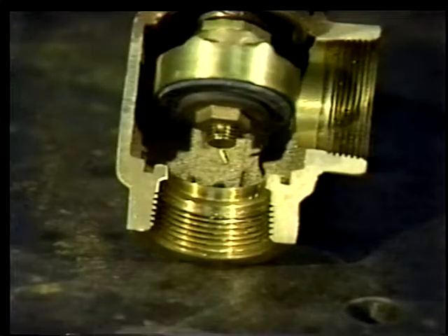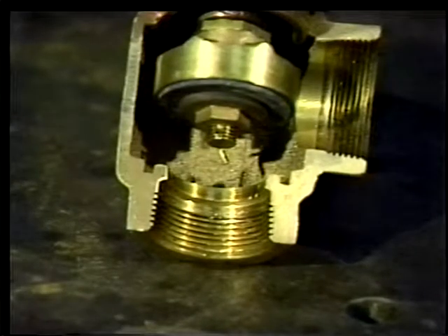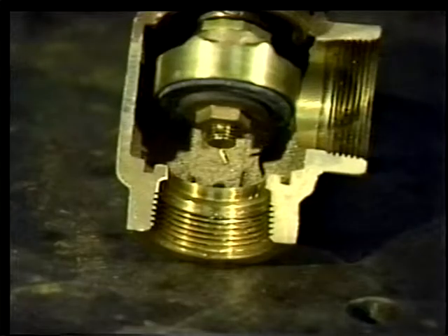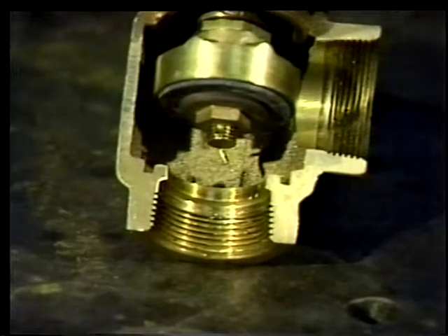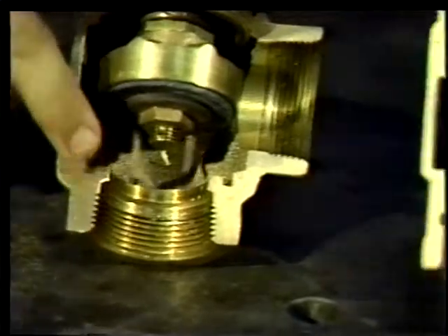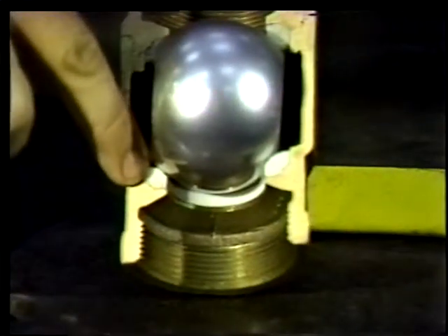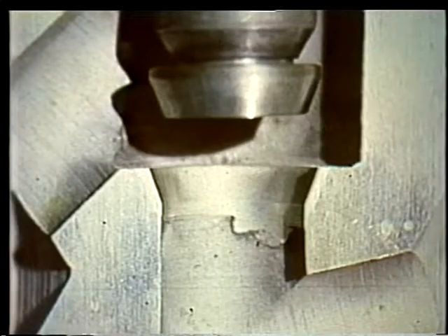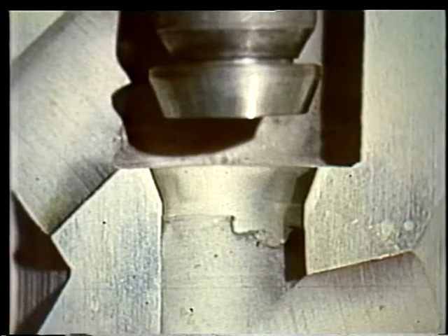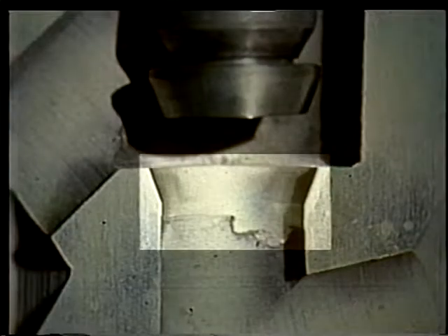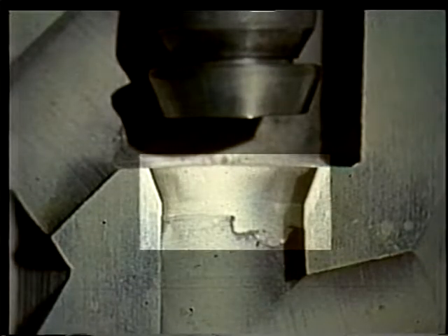The materials used in constructing a seat will vary depending on where the valve will be installed. For low pressure, low temperature systems such as service water, the valve seat may be made of bronze or a Teflon type material. In systems requiring high temperatures and pressures, the seating area must be very strong. Stellite, a commercial name for an extremely hard metal, is often used. This metal has proven to be highly resistant to damage due to leakage of steam.